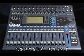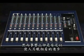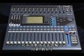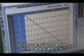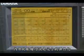Looking first at the internal benefits of a digital mixer, although the channel strip would appear to be much like its analogue cousins, there is one major enhancement here. Just because you plug into, say, channel 1 on the mixer, you can actually route that input through any channel you like. The internal routing, in other words, is totally flexible.